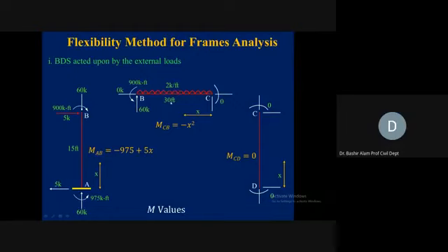That's 2 times 30 divided by 2, which is 30. This 30 kip we are putting in the vertical direction. Then it has to be in equilibrium to the right of joint C, so if it is upward here, it will become downward. So how are we going to balance this at joint C, or D, because at D we don't have any support? So this 2 kip per foot cannot travel to the right where we have joint C. It has to be balanced by B only.